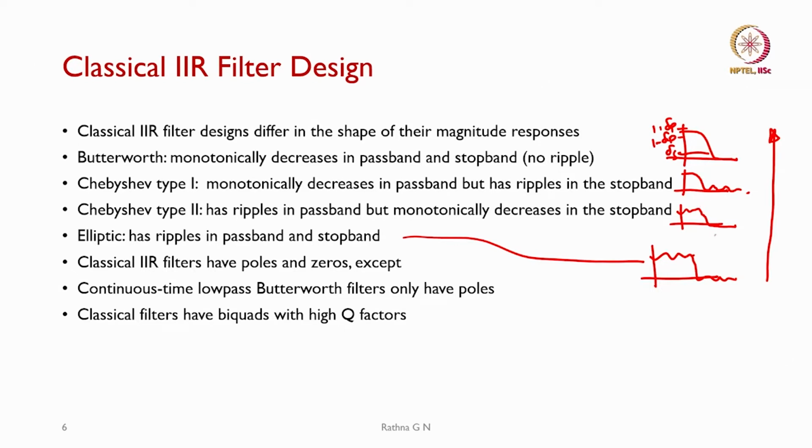It depends on which frequency you want to meet. Most of the time when we use the impulse invariance method, it is better to go for Chebyshev 2, which is in between in order. I can allow a little bit of ripple in the pass band, but I want to meet the flat response in my stop band, so that no aliasing is going to happen.